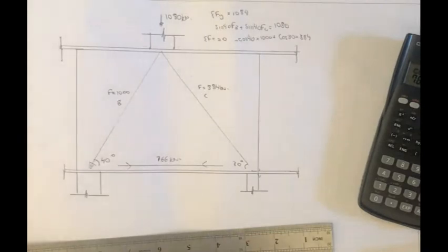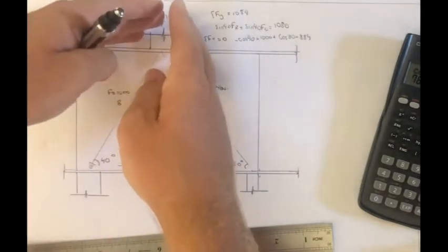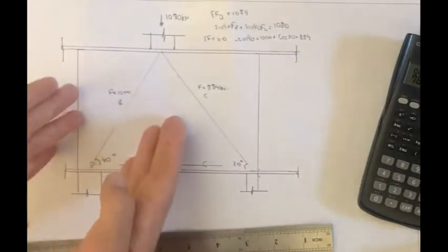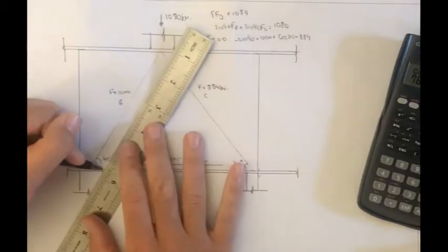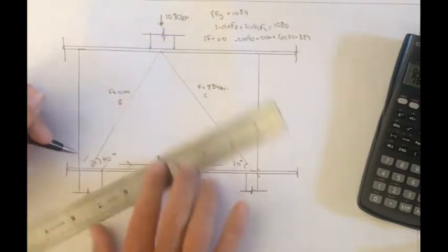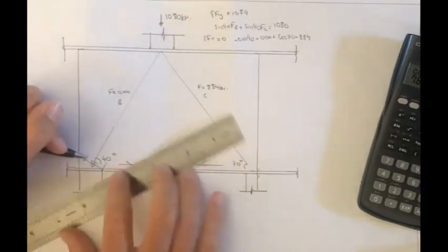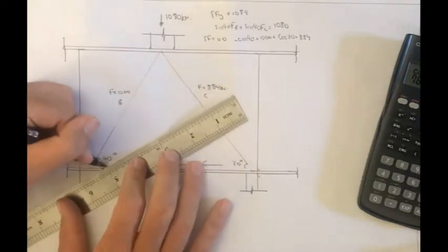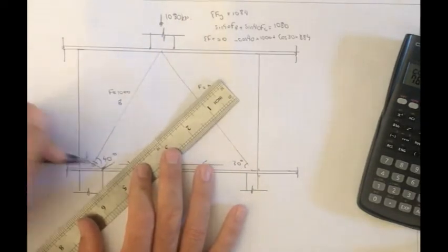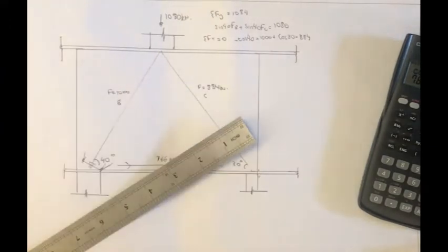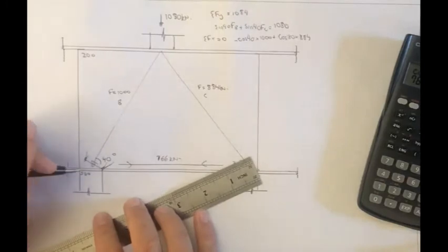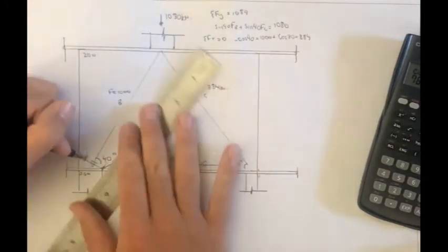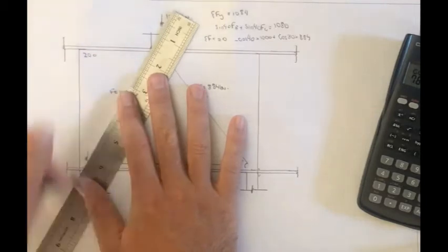So first of all, the strut, as we mentioned, we have a bottle-shaped strut coming out like this and then back down. We'll cover the bursting reinforcement soon, but for the strut, best off taking the smallest dimension to start off with. So you're going to have the node coming out like that, but we'll just take the most critical dimension, which will be this. So say if we've got a 200 thick wall and a say 500 thick column here, that means the strut will take dimensions of 500 there.